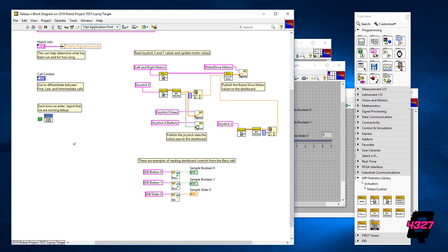In case this is not already open, remember to press Ctrl and E at the same time to see the code underneath the gray face. Here we will need to call back that same motor we just brought into existence in the Begin VI. To do this, let's go get that motor palette and get the icon with the arrow coming out of the numbered page. Next, from that same palette, you'll want the Set Output icon. Make these two neighbors and let's wire them up. Reminder that you need to set the name of the motor to the exact same name used in the Begin VI.